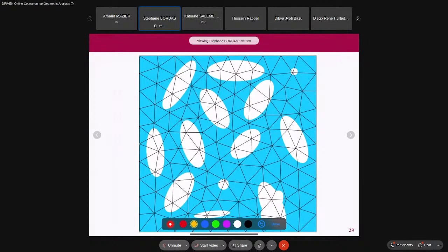All right, so the basic idea is like that. We would like to embed the geometry inside a mesh, and the mesh is supposed to remain fixed, right? For example, here we have an interface, and that interface is not conformally meshed. So, for example, here you see this element. I hope you see what I'm drawing. The element is actually split, and the interface does not know where the elements are. The elements that are inside will be activated. If an element is fully inside, like this element, it will be fully activated. Some elements will be split, like for example, that element.